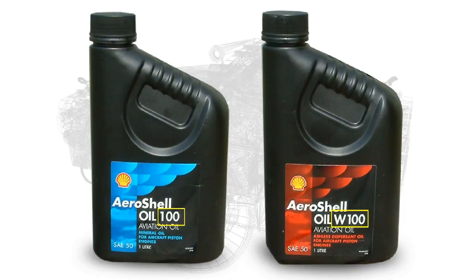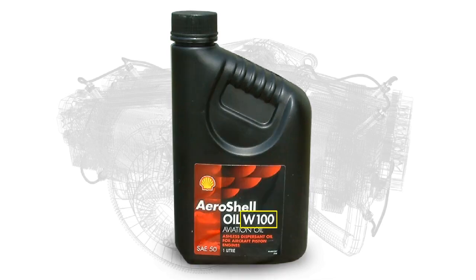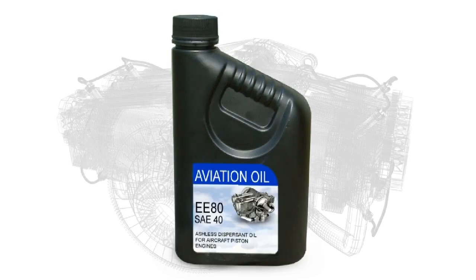Straight and compound oils are both identified by the viscosity numbering system, but a compound oil will have additional lettering as well as the number. Thus, a bottle or can containing a straight oil with a viscosity of 100 would have only the number 100 marked on it. But a compound oil of the same viscosity may be marked AD100, EE100, or W100. The actual lettering used varies with the oil's manufacturer.